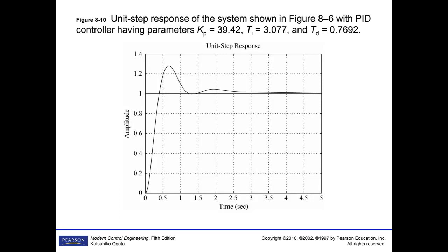In the meantime, that minus 1 and minus 5 here are free. They couple together, and they constitute something similar to a second order root locus curve, which is far away from the origin. It's nice. And these are the dominant poles, by the way. The poles near the origin are almost zero now, so there are no dominant poles there.